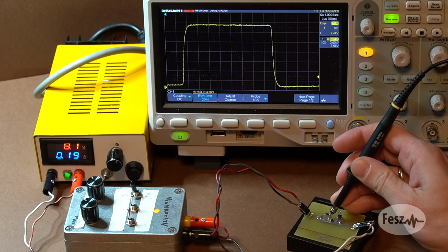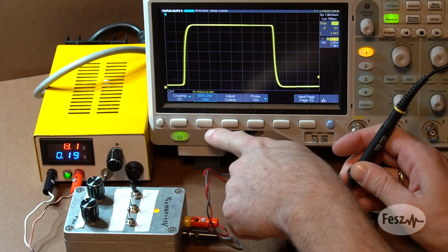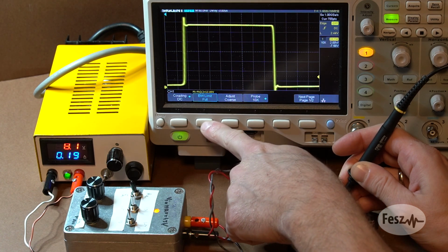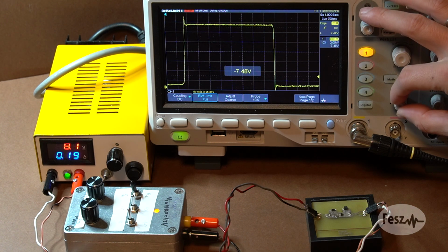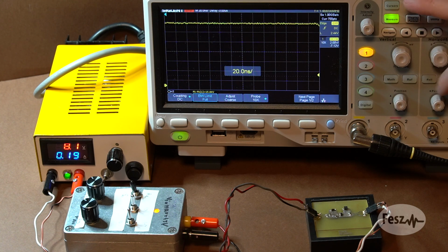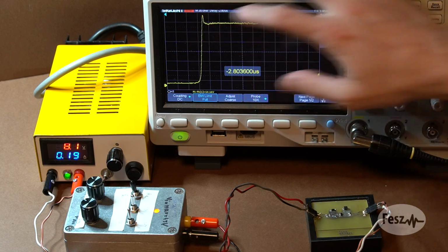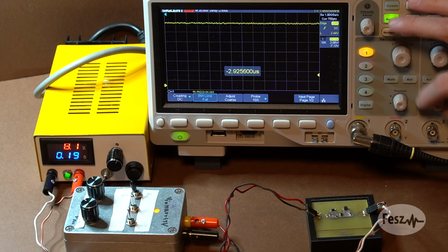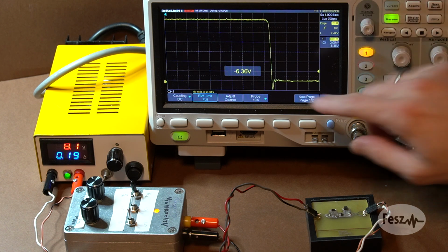Coming now back to the real circuit, when your measurement equipment has sufficient bandwidth, and while the converter design is bad enough, another interesting phenomenon becomes visible. Other than the square wave, which is not really square, you also have some high frequency oscillations appearing, at a frequency that's unrelated to the main switching one. Now, these oscillations can be more or less severe, but they will be problematic nevertheless.